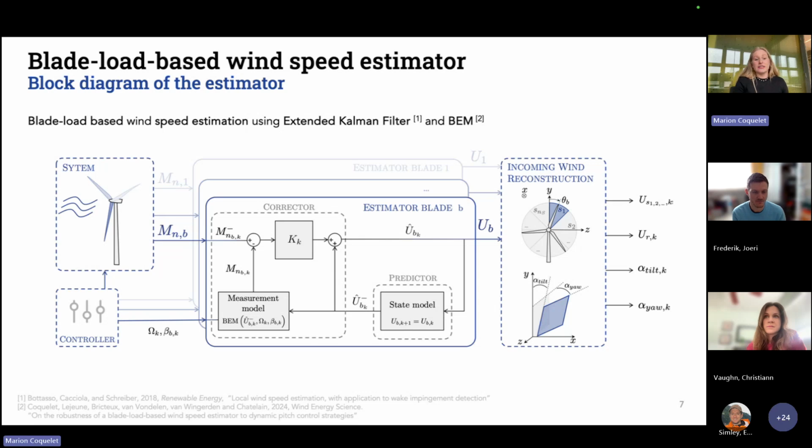Now, what I would say is that in terms of the system, when we use the LES, all those dynamic effects appearing at the blade, we're able to capture. With the BEM, it's basically just a filter on the inductions. So I would trust the LES better and believe that it is closer to my reality for sure. Also, in terms of the inflow that you can provide, we can really have turbulent inflows, wakes, shear. For the BEM, it's another story.